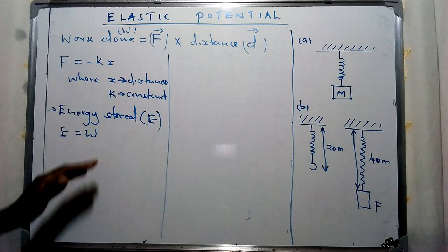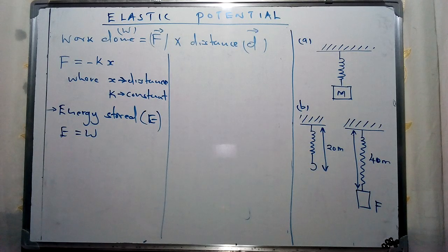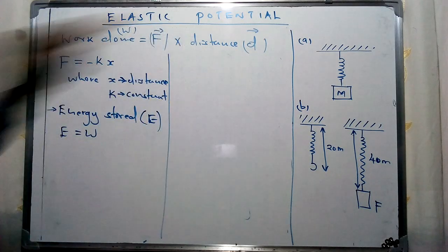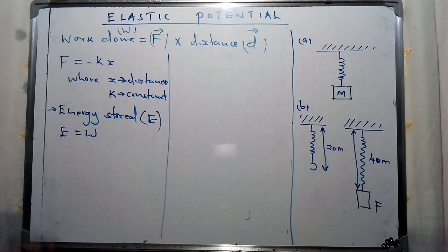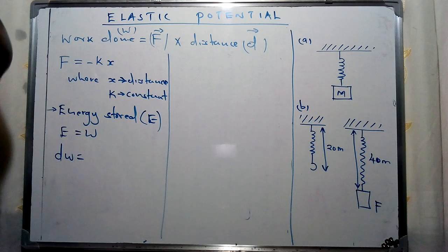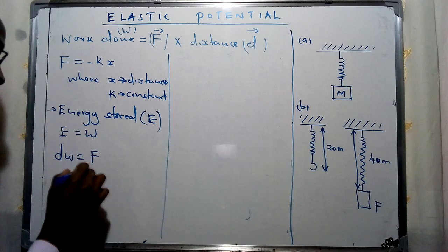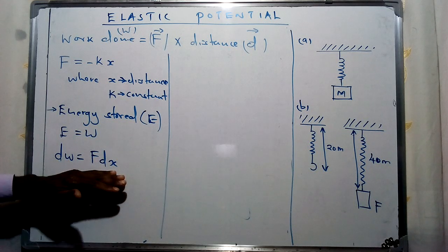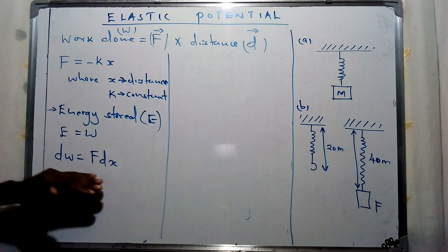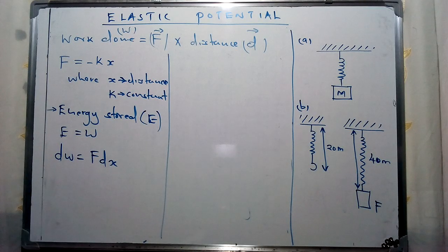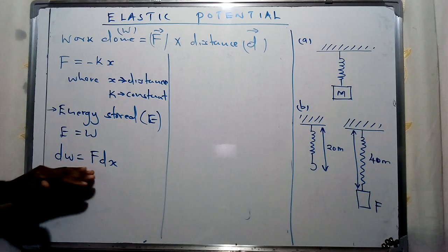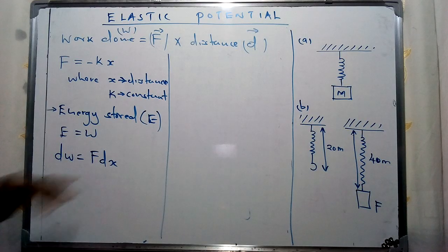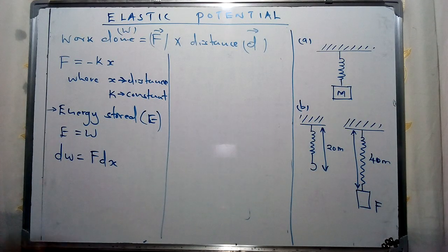We can analyze this concept of work, and in finding this work, it is going to be equivalent to the elastic potential of this spring. We said that we can consider an element of work, dW, which is the force times a small segment of distance stretched. To find the total work done, we integrate over these small elements of work, that is, the force times the elements of distance, summed over the distance achieved.